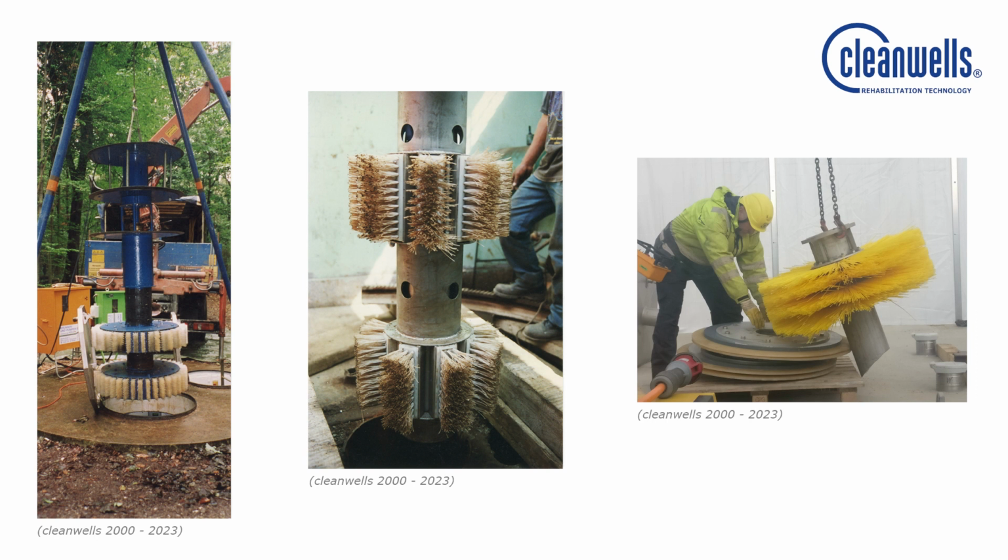Mechanical cleaning by brushing or jetting is successful as long as deposits are soft and of low crystallinity, as the heaviest clogging adheres next to the screen. Often, the structural condition of the well interior can only be inspected in detail by CCTV after the mechanical cleaning in order to determine the further rehab strategy.